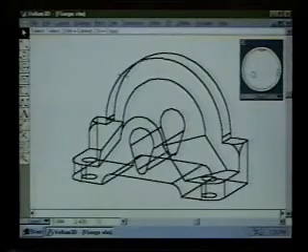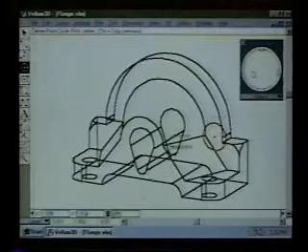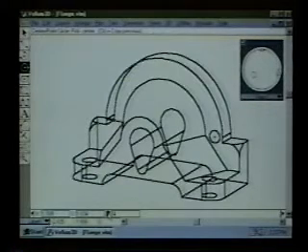The next thing to do here is to put a bolt pattern along this flange area here. So I'm going to go in and pick my circle tool, and I'm going to wake up some points here, and I'm going to draw a circle. Now you can even draw things that are far too large and then specify a size like 0.4, and when I hit enter it becomes exactly that size.